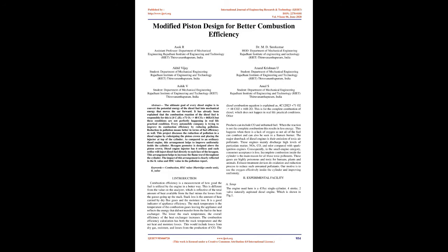Hexagon geometry is designed above the piston crown. The diesel engine injector has 6 orifices and each orifice will inject diesel fuel directly to each face of the hexagon. This arrangement helps to increase the flame travel throughout the cylinder. The impact of this arrangement is clearly reflected in the K value and HSU value in the pollution report. Keywords: combustion, HSU value, Hartridge smoke unit, K_value.